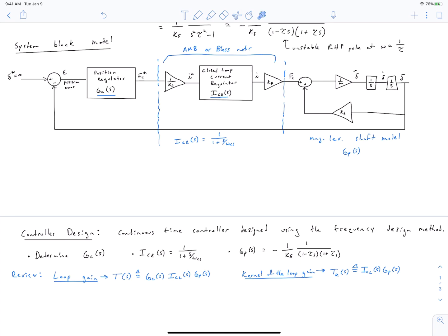And we're noting the gains, the transfer functions of various components of our system. So this region of our system has this transfer function right here, where I changed this omega p to be omega ci to indicate that it's the pole of the current regulator. And then we've got our plant right here that we've derived for the magnetic bearing model.